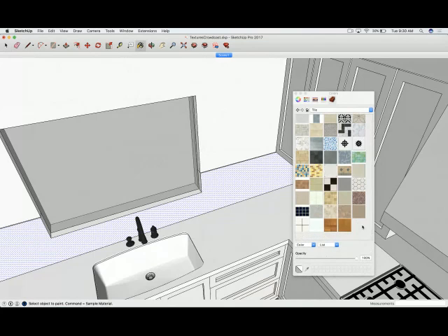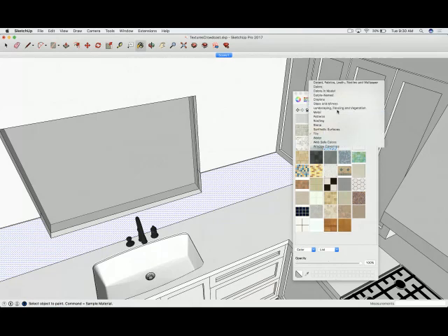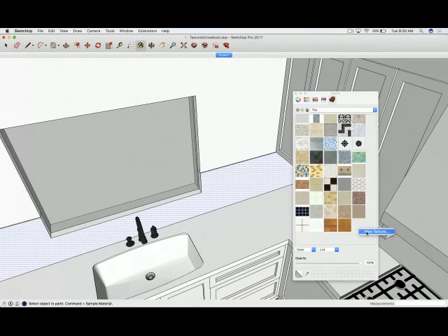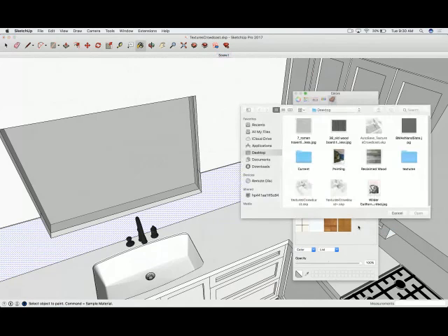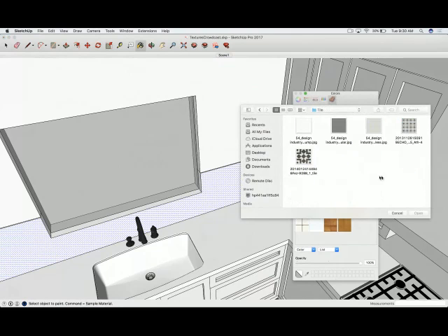So I'm on a Mac. So I created a blank space here by pulling this down, or you can do it under tile. You can do it under colors and model. I'm going to right click on this space and say new texture. And it's going to bring up those folders. I'm going to go in my textures area, tile. I'm going to find this tile, open.